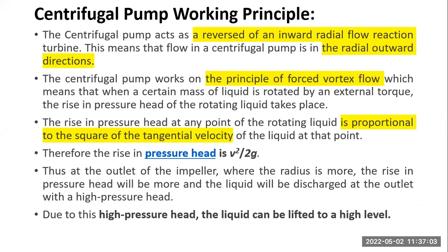The main point of this pump is that the centrifugal pump works on the principle of forced vortex flow. So anyone please tell me, what is forced vortex flow? I think you have studied it in physics or fluid mechanics also. In this case, a certain mass of liquid is rotated by an external torque. Then the rise in pressure head of the rotating liquid takes place.